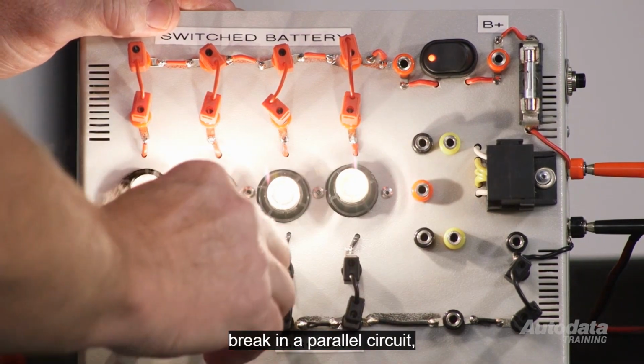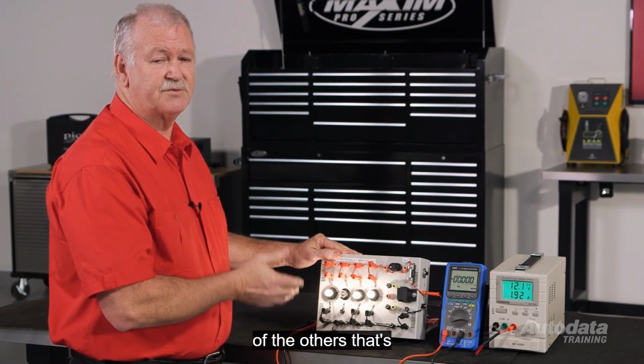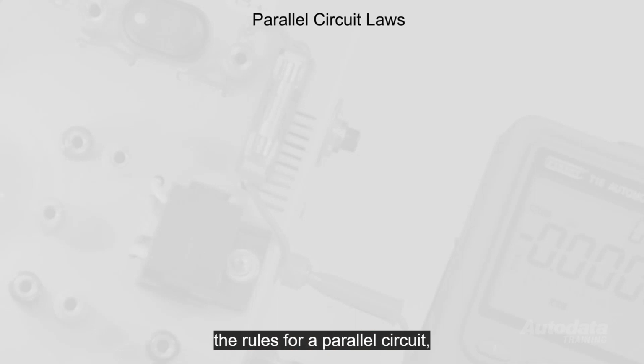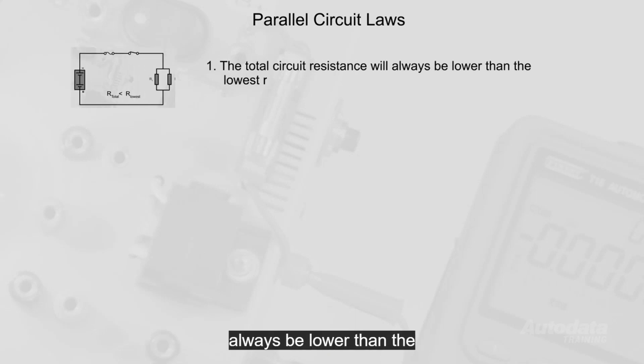If I create a break in a parallel circuit, it only affects that branch. It doesn't affect any of the others. That's one of the advantages of a parallel circuit. So the rules for a parallel circuit. The total circuit resistance will always be lower than the lowest resistance in the circuit.